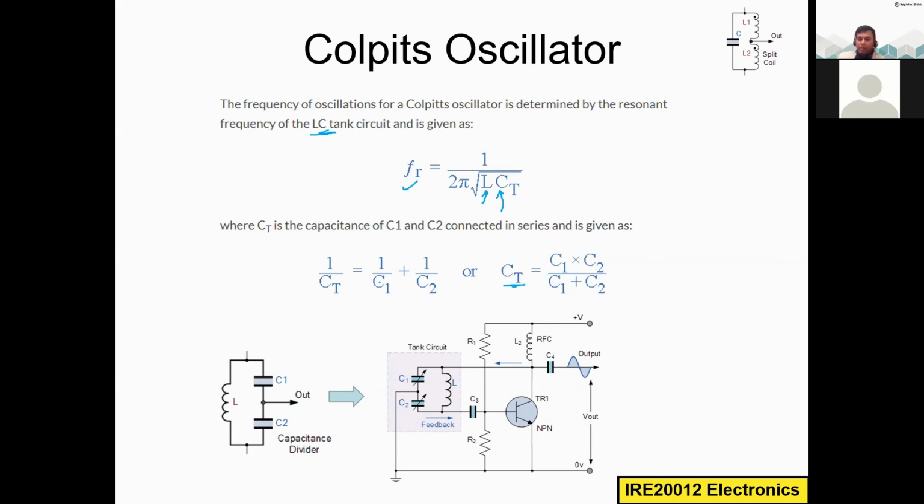So 1 divided by C1 plus 1 divided by C2. So that is the effective capacitance reciprocal. If you modify this equation mathematically, you will get the effective capacitance of C1 and C2. So it's a little bit different between the resistor, inductor, and capacitor. You should know this difference. You are an electronic or electrical engineering student, so you should know this.